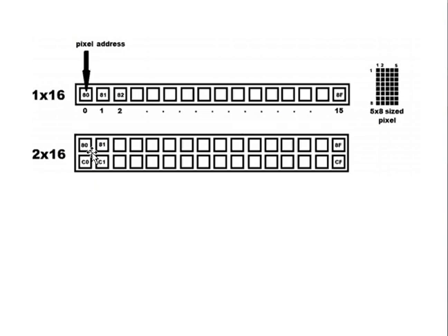So altogether 32 characters you can print. And the main reason why we are using LCD rather than a 7-segment LED is the characters you want to print, probably special characters, Greek letters, Latin letters, all those can be effectively transferred with the help of this kind of module. Whereas if you're using LED, there is a restriction. For example, with good resolution you cannot print it.